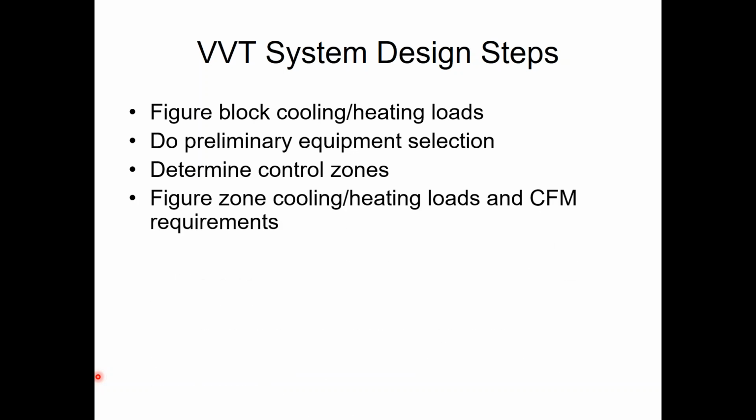And then I'm going to do another load calc for the room-by-room load calcs. I'm going to need to do that at some point anyway, even on a non-VVT system, in order to figure out what size ducts go to each room. I don't need it to know my preliminary equipment selection because I just want to get something in the ballpark so I know if I'm starting to think about offering my clients rooftops or air handlers or some big massive chiller plant, right? But at some point I've got to do room-by-room load calcs so I can size the ductwork to the zones.